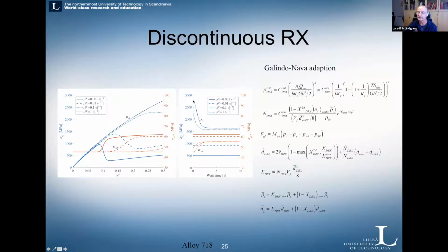But if you stop and wait, the flow stress goes down, because you trigger the new nuclei for the grains, but they need some time to grow because there's a limited growth rate due to the motion of the dislocation, or the grain boundary. So therefore, it includes dynamic as well as metadynamic recrystallization. So I prefer just to call this continuous RX.